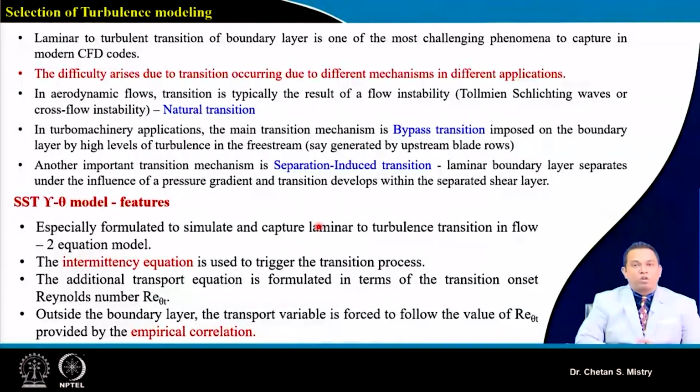In an actual engine also, this turbulence intensity will be ranging maybe 5 to 10% of turbulence intensity. What kind of flow is flowing inside my engine is basically giving us an idea in the sense of turbulence intensity. And this turbulence intensity varies with different kinds of flow configuration, different kinds of flow structure that is happening between the stages. So we need to be very careful which stage we are analyzing.